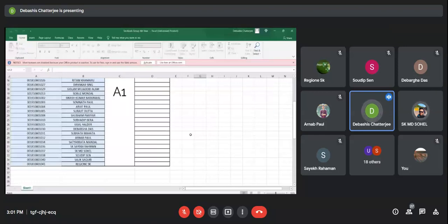So what is the rating of the machine? 1 kilowatt. Okay. Power rating is 1 kilowatt. I'm repeating again. 3-phase, 230 volt, 50 hertz, 1 kilowatt, 730 RPM, 0.85 power factor, 45 degrees centigrade temperature rise above ambient, and you have to design for maximum efficiency. Okay, sir. That's all.